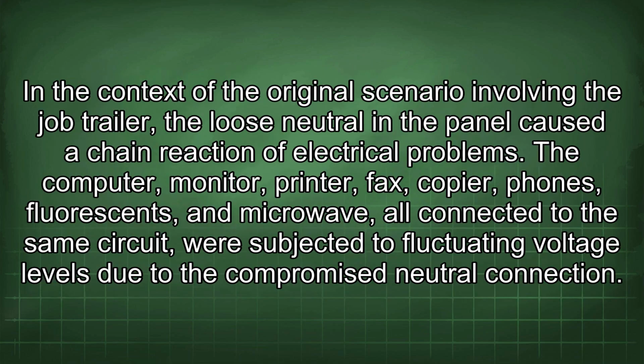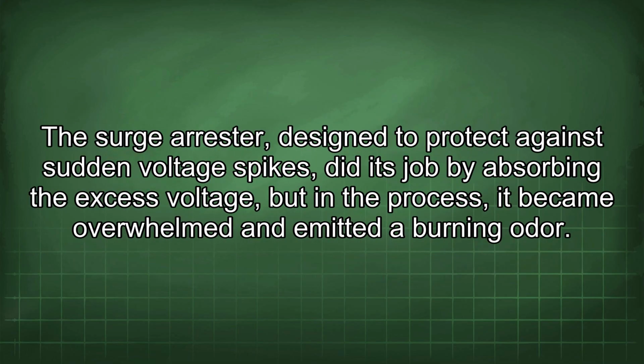In the context of the original scenario involving the job trailer, the loose neutral in the panel caused a chain reaction of electrical problems. The computer, monitor, printer, fax, copier, phones, fluorescents, and microwave, all connected to the same circuit, were subjected to fluctuating voltage levels due to the compromised neutral connection. The surge arrestor, designed to protect against sudden voltage spikes, did its job by absorbing the excess voltage, but in the process, it became overwhelmed and emitted a burning odor.